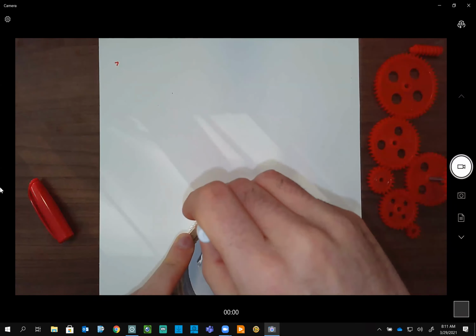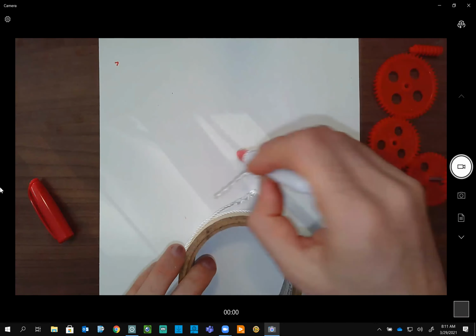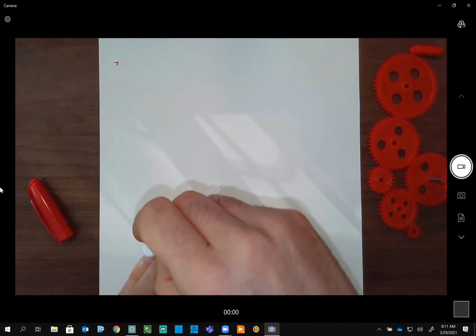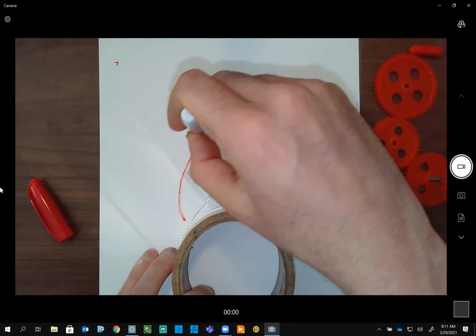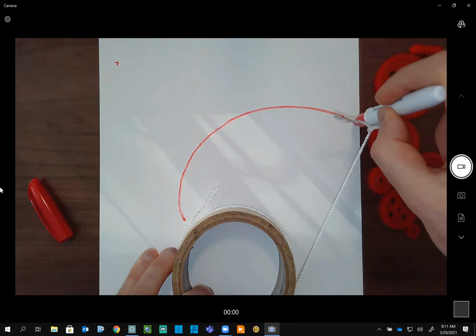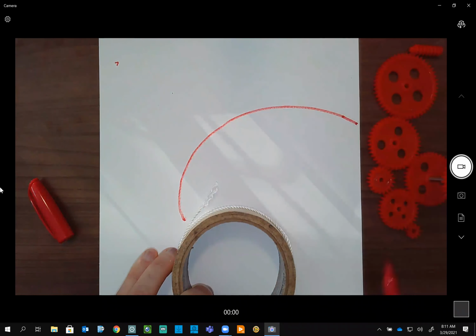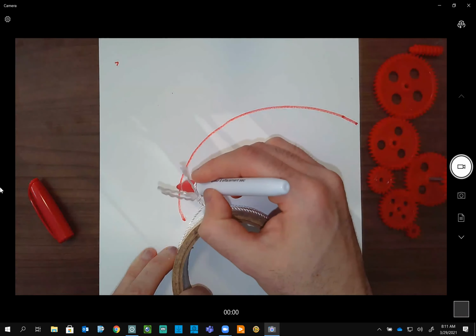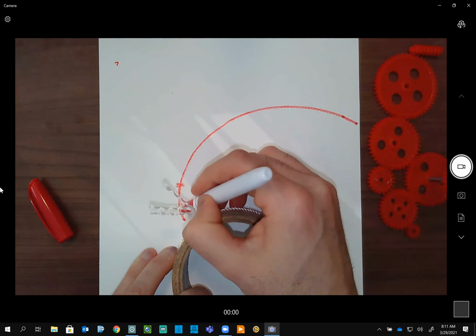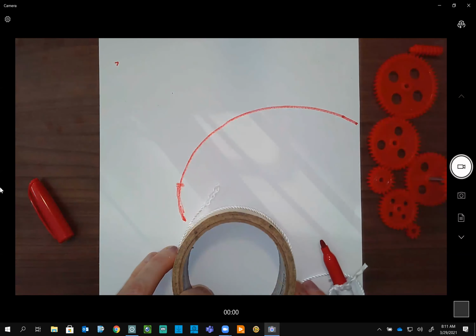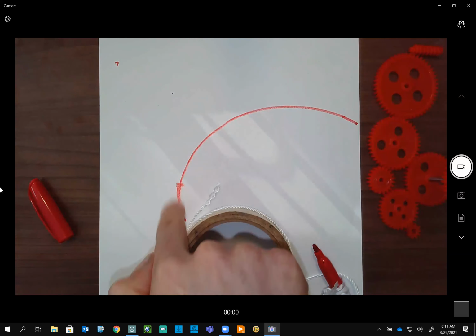So what I do now, this cylinder is fixed, and while the string is under tension, I open it up. All right, so this is the involute that we can create. Now for a gear, all we need is a portion of that, not all of it. A portion of this one gives me the profile for, let's say, one tooth at this point.